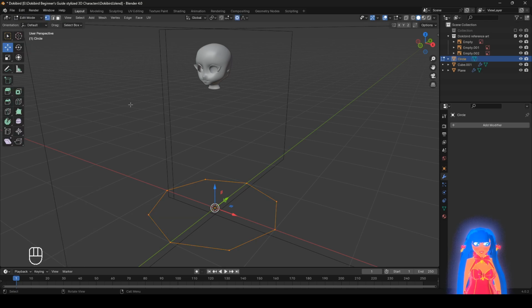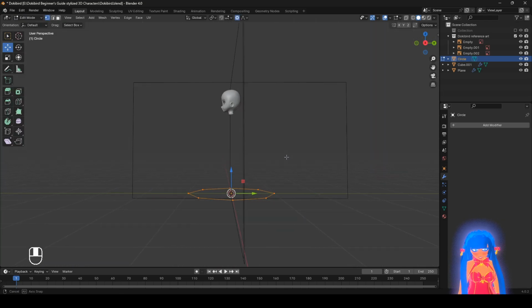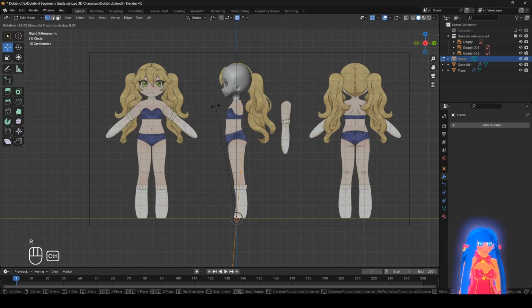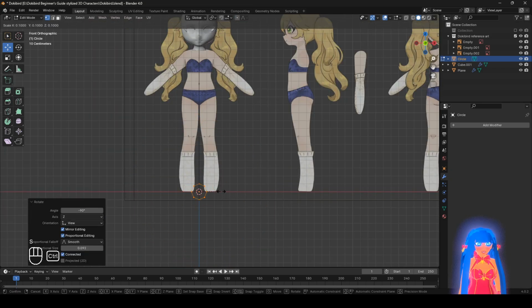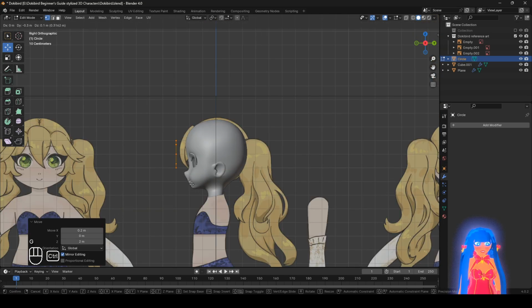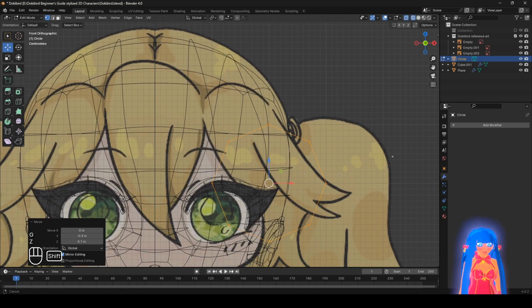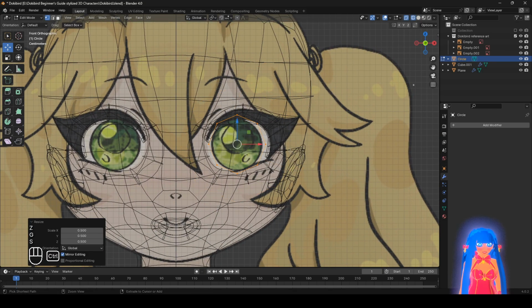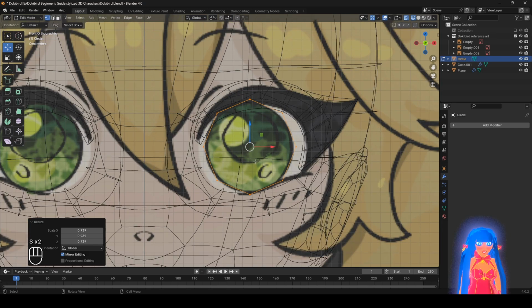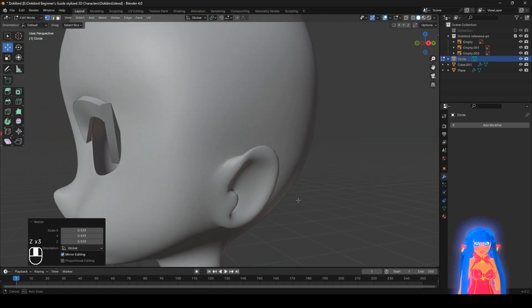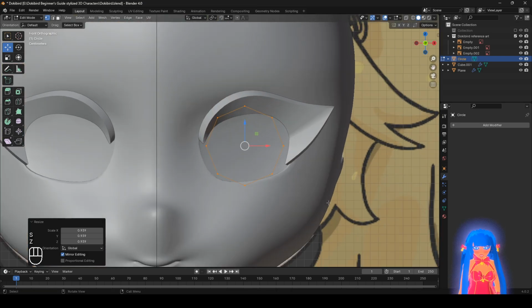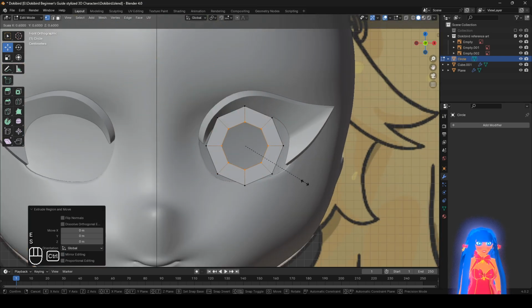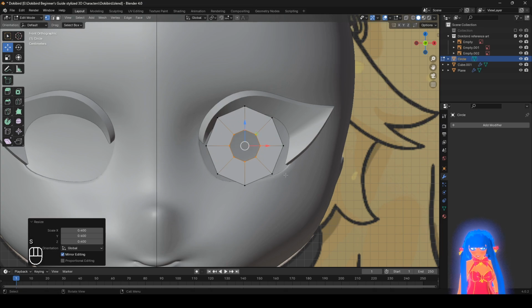After that, go into edit mode. Then I'm just going to middle mouse button, Alt, snap right there, then do R. And make sure you have this off. And just do S to scale, about right there. Just G to move and hold Alt to get exact measurements, if you're into that kind of thing. And just S to scale. All right, this is a round eye, so it's different. If it's an anime eye, you can just S, Z, make it bigger. But for now, just E, right click, S to scale, about right there, then do F.